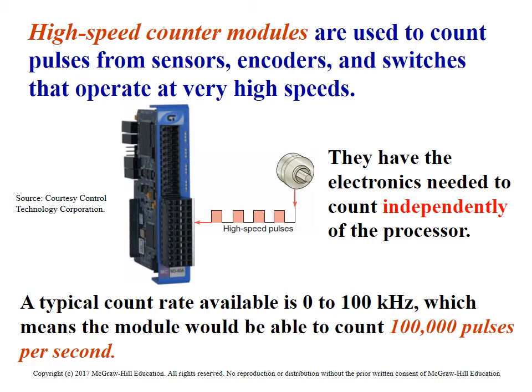So the information being fed to the PLC is not accurate. To solve that problem, they've created a high-speed counter input card. We call it an HSC, or high-speed counter card. What that does for us is that it captures every on and off signal and stores locally in that card the number of times it's gone on and off, and then when the PLC gets a chance to read that card, it goes out and asks, how many counts do you have now?